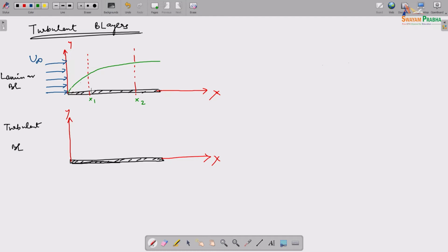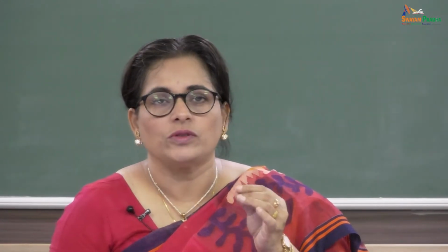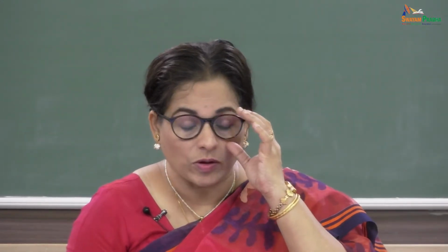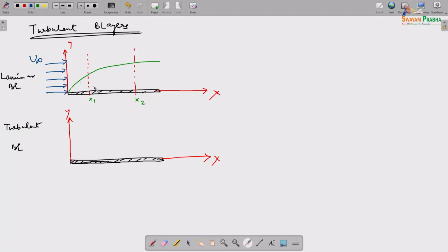Then the velocity profile, well actually what happens to the flow? For example, this streamline that you see here, the first one, what happens to that here? Well, it does not move at all, it comes to a stop. The flow which is nearest to the solid obstruction here, which is the flat plate, the fluid which comes in contact with that will come to a stop, and that is basically because of the viscosity. So, there is no velocity component here. So, this actually is 0.